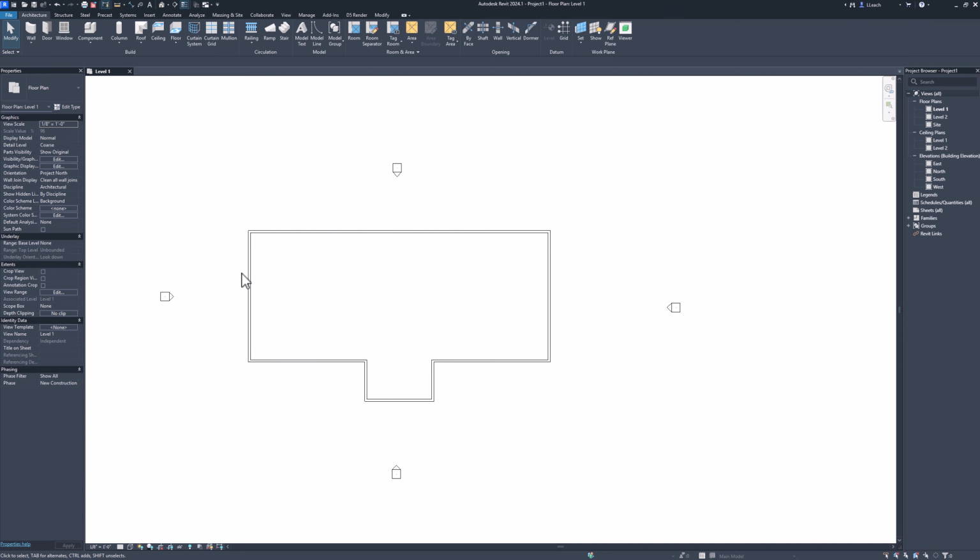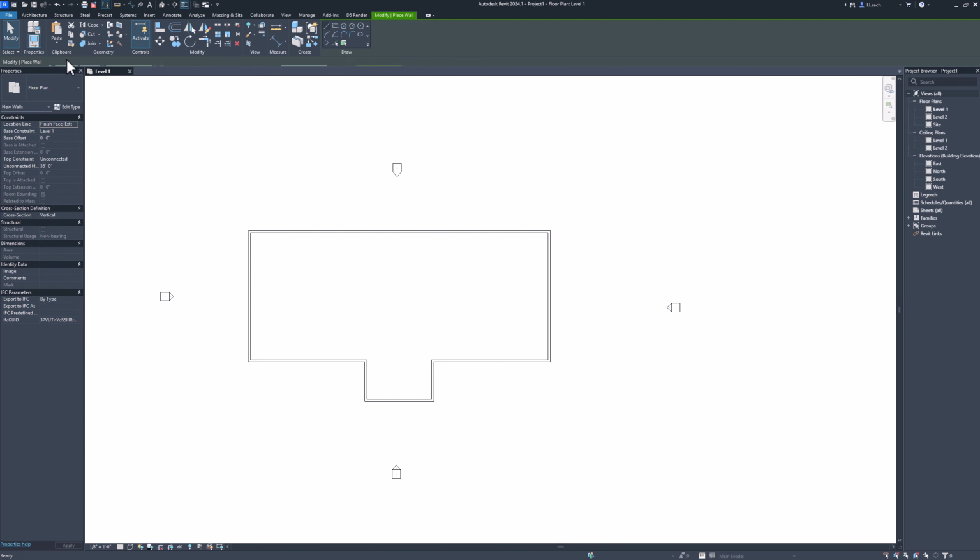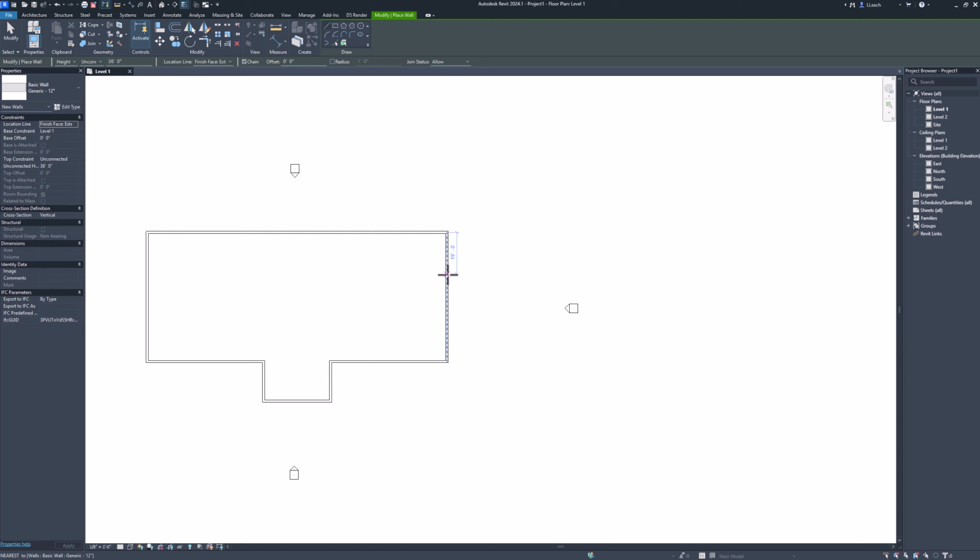All right, so now I'm going to draw these little walls on the outside. So again, go to wall. I'm using the same wall here. So I'm going to come over to the side. I'm not worried about dimensions really. I'm going to go over to there. That's going to be 9'4" to the right. So 9 space 4. And then straight down 22.